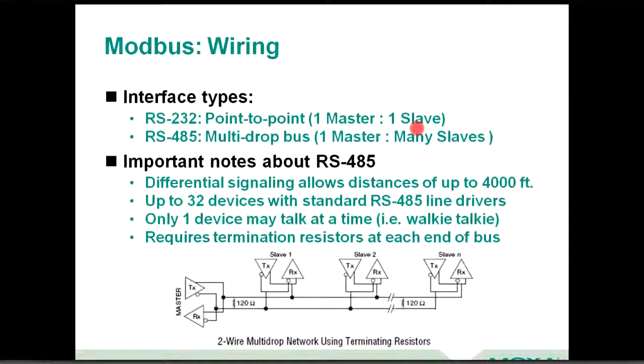If you want to have more than one device, you have a little more complex configuration here using RS-485. RS-485 has some unique abilities in which you can share amongst multiple devices a pair of wires. Some people will call it multi-drop or cascade. Basically, it means that that master has the ability to talk and to read and write different slaves.